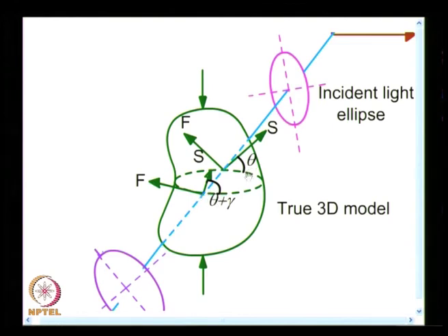These are optically determined, and this is called the primary characteristic direction, and this is called the secondary characteristic direction. You call gamma the characteristic rotation, and you will also have 2 delta, which you call the characteristic retardation. So, you attach a new terminology called characteristic parameters.